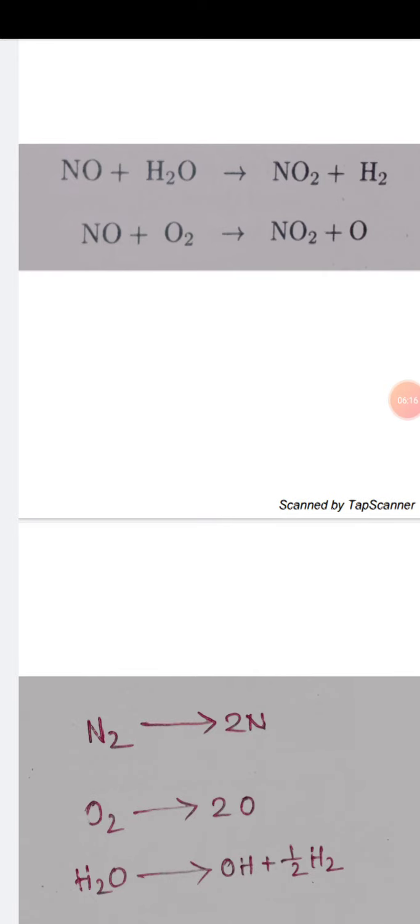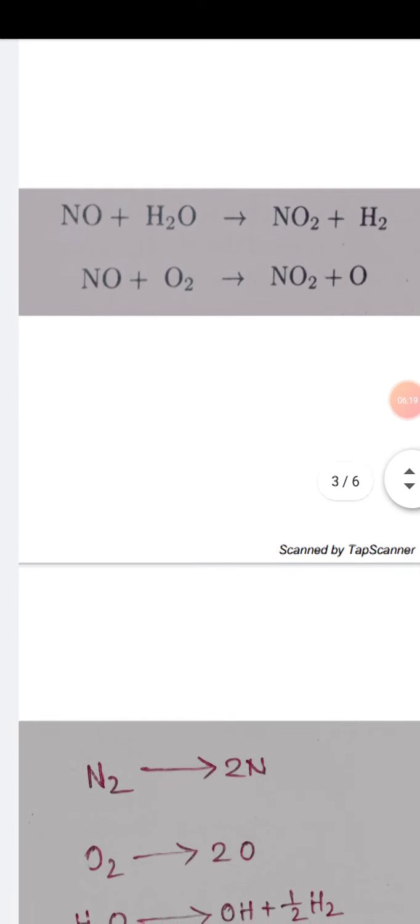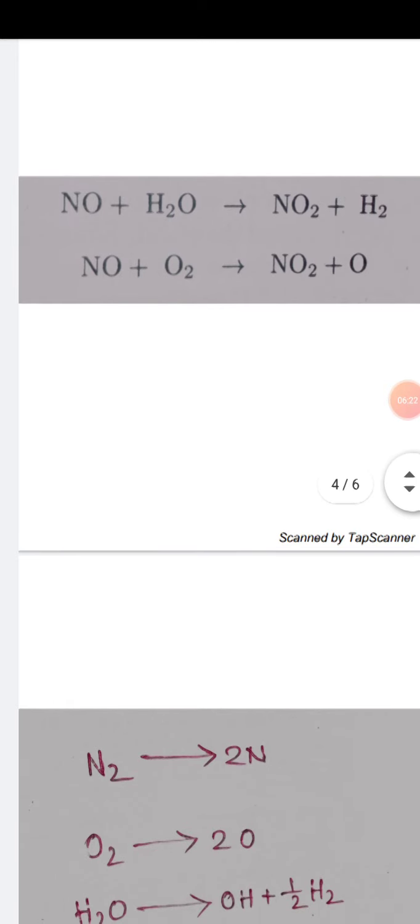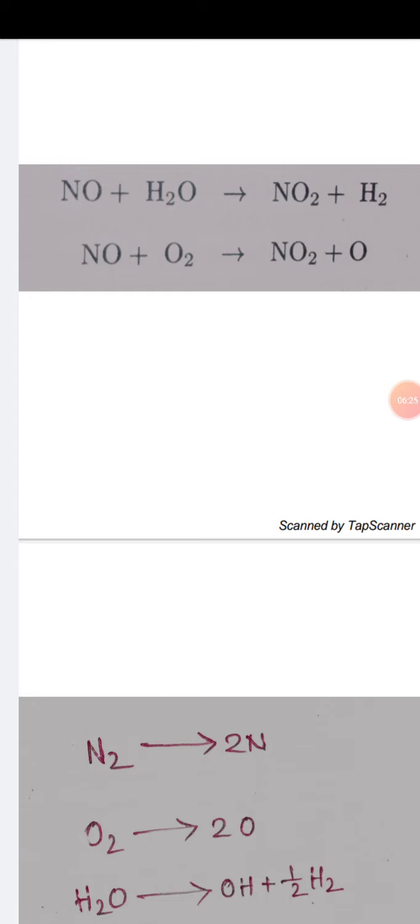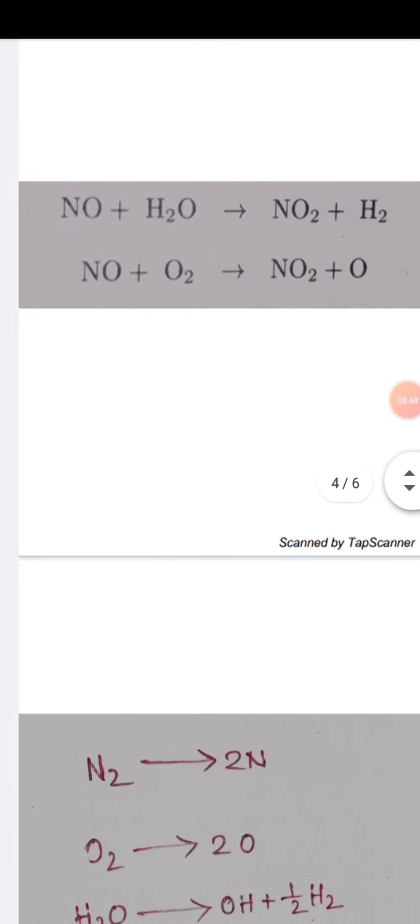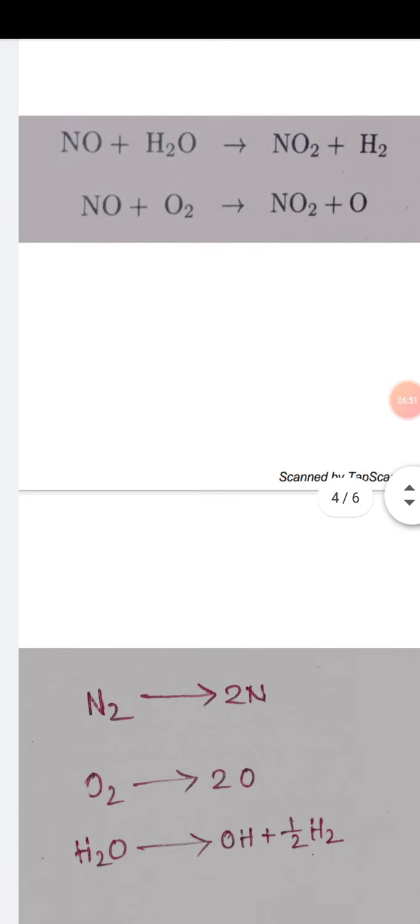At low temperature, atmospheric nitrogen exists as a stable diatomic molecule, and therefore only very small trace amounts of oxides of nitrogen are found. However, at the very high temperatures that occur in the combustion chamber of an engine, some diatomic nitrogen breaks down to monoatomic nitrogen.